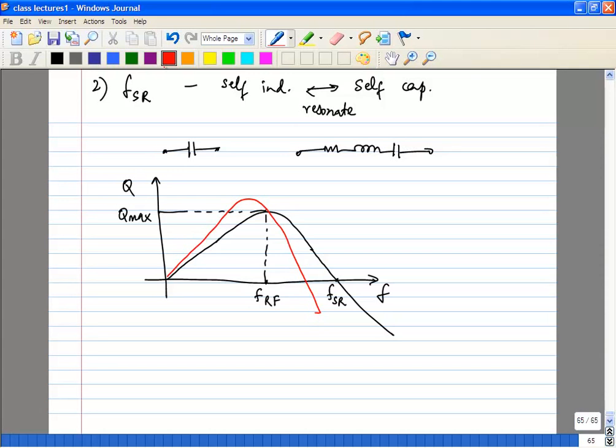Yes? Suppose you are designing a transmission line for a given substrate with a given epsilon value. You'll have a particular track width for a given impedance. Now suppose this has to be interfaced with a given transmission line. So that track width will be governed by the impedance that we want.